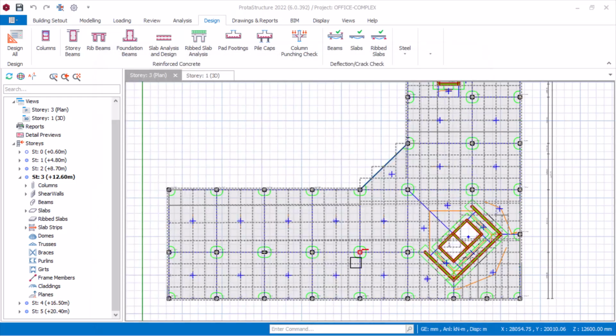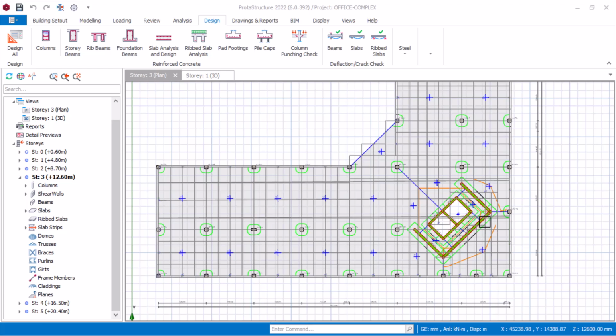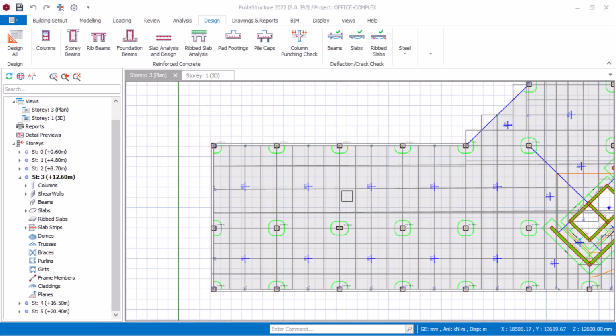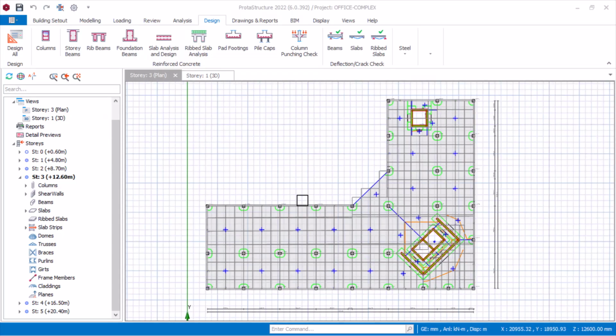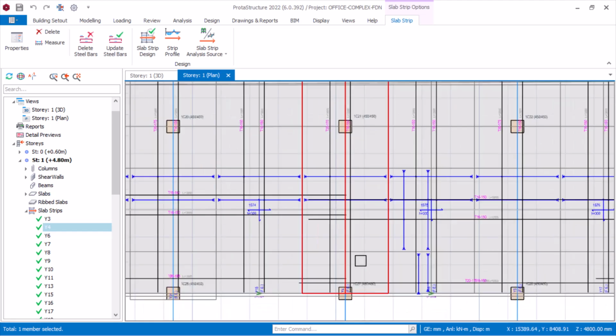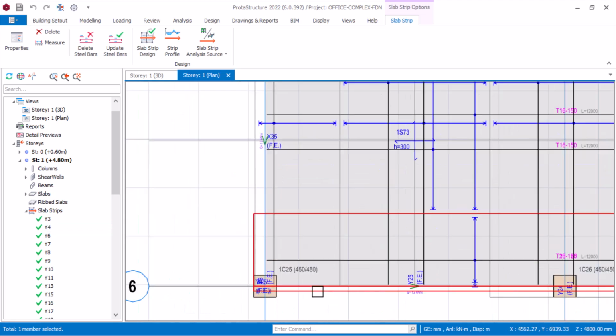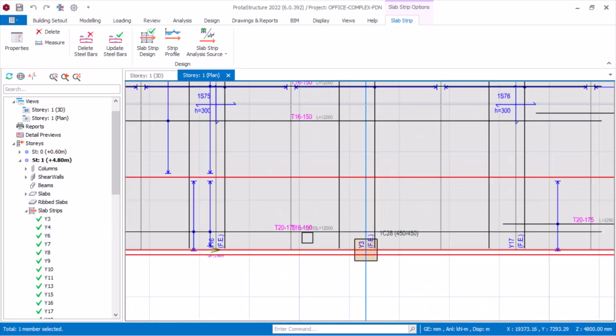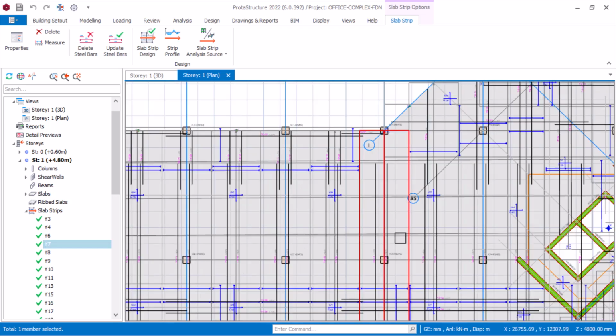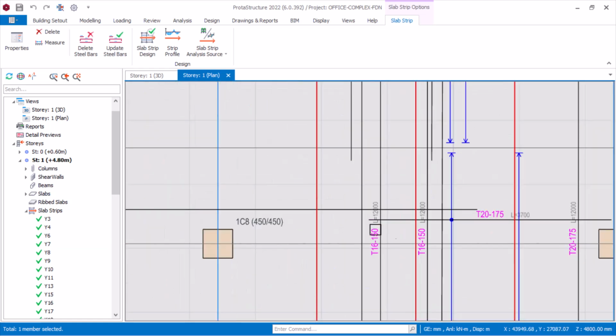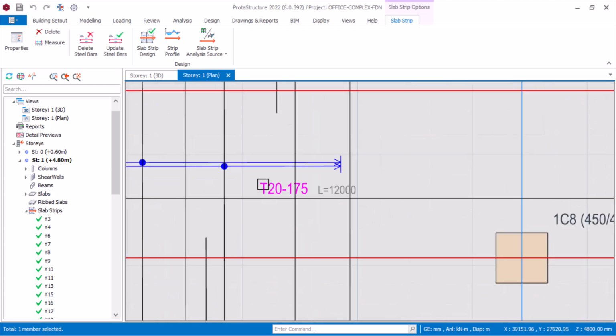So you have to calculate the punching perimeter for each of the columns. You know the punching region. And then when you have known the punching region, you will reinforce that region separately. This reinforcement is called the punching shear reinforcement or the punching reinforcement.